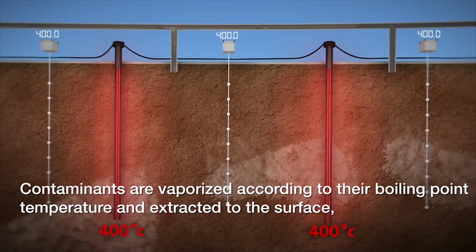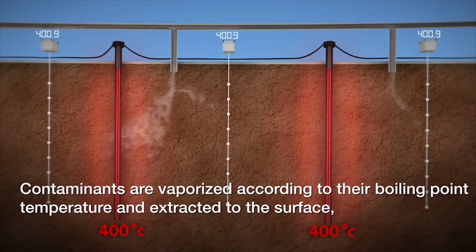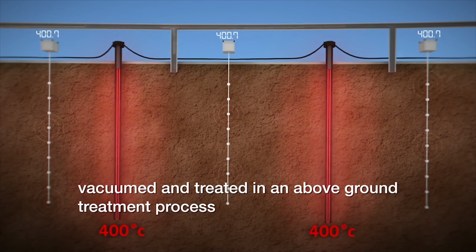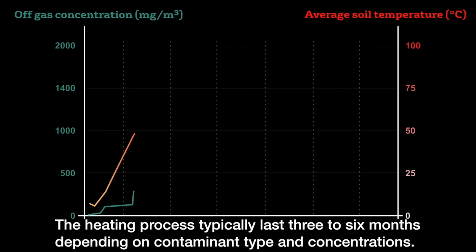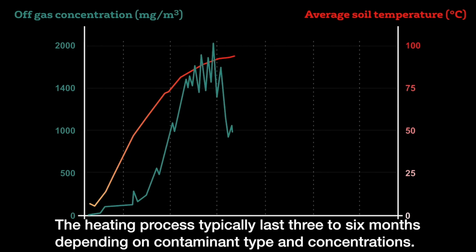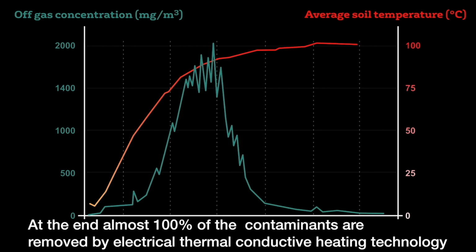Contaminants are vaporized according to their boiling point temperature and extracted to the surface, vacuumed and treated in an above-ground treatment process. The heating process typically lasts 3 to 6 months, depending on contaminant type and concentrations. At the end, almost 100% of the contaminants are removed by electrical thermal conductive heating technology.